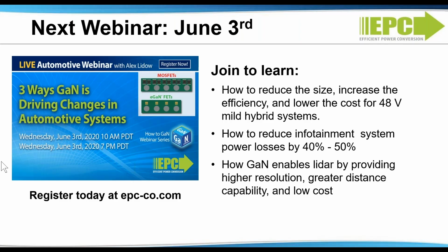Is it possible to use these devices in boost converters? Absolutely. I think the same advantages that you see in a buck converter are true in a boost converter, which typically, most of them are hard switched. And if you boost to 48 volts, you need something like an 80 to 100 volt device. So yeah, we have lots of customers doing boost converters with these FETs.